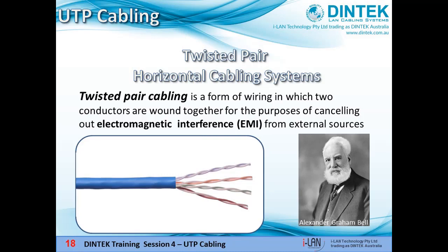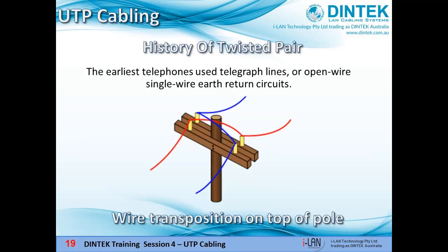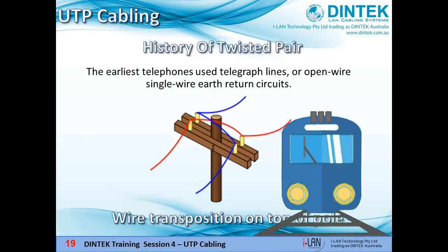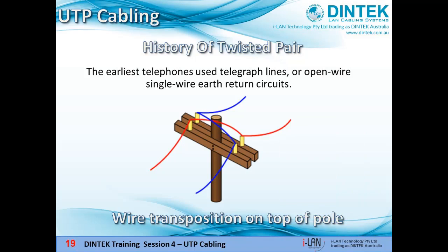Basically, a pair of wires forms a circuit that can transmit data. The pairs are twisted to provide protection against EMI as well as crosstalk, which is noise generated by adjacent pairs. Back in the 1880s, with the earliest telephones and telegraph lines, when electric trams were installed in many cities, they started getting noise into these circuits. This caused the telephone companies to convert to balanced circuits, which had the incidental benefit of decreasing attenuation, which increased range, so everyone was happy.